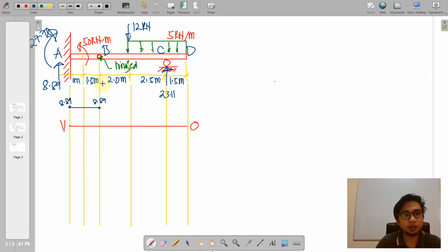So anyway, your hinge now is attached. Therefore, we still disregard the internal forces along your hinge connection. And just the same, it will remain to be 8.89 until we deduct 12 units downwards from this ordinate. So we'll be having negative 3.11. Of course, we'll place here the closing line.